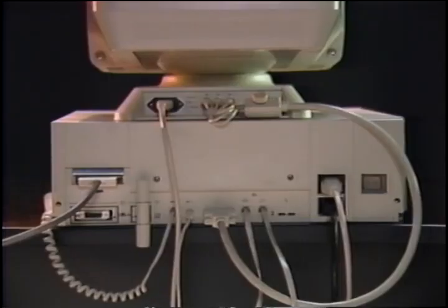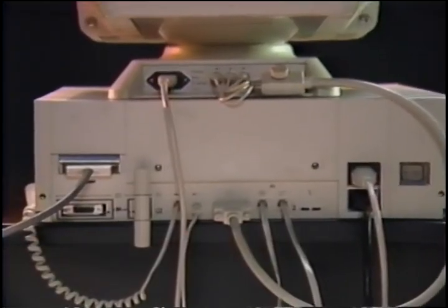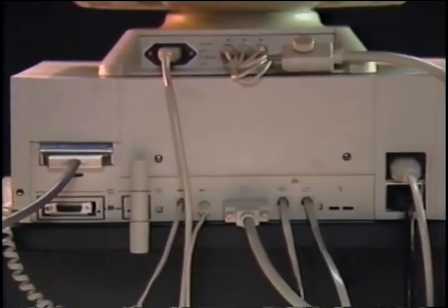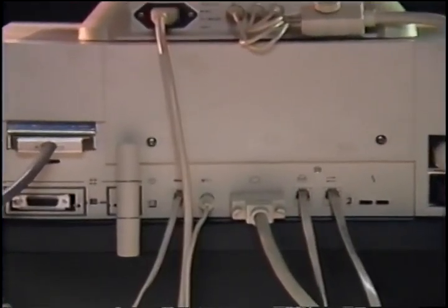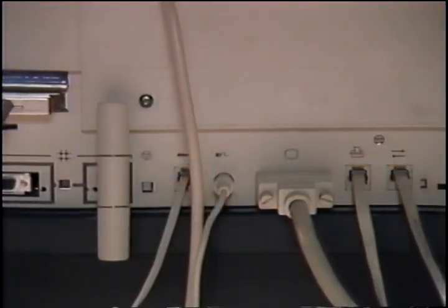For most troubleshooting, the power-up tests reliably pinpoint fatal errors. If necessary, more detailed information is available in console mode. Console mode is entered with the halt switch and is indicated with this prompt. Enter test 50 to redisplay the power-up results in a configuration table. Also displayed with the CPU name and ROM version is the system's Ethernet address.